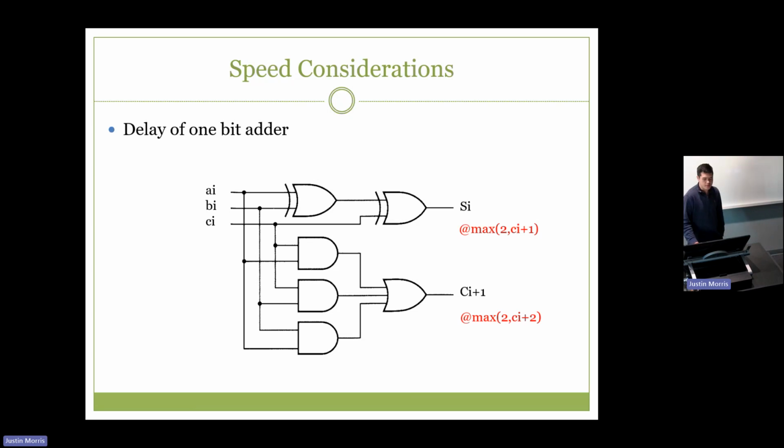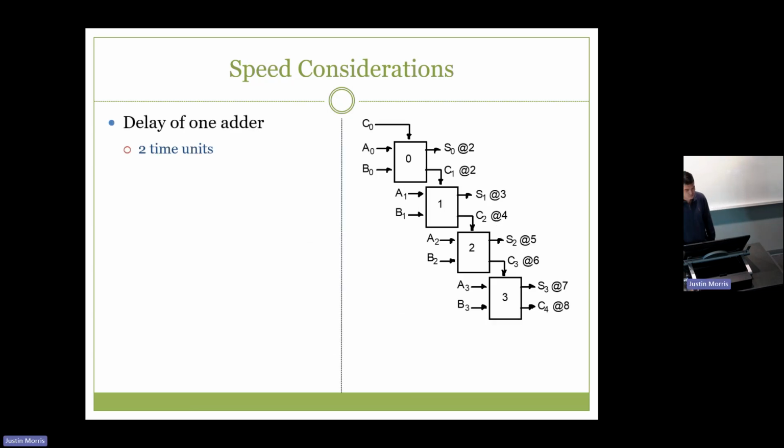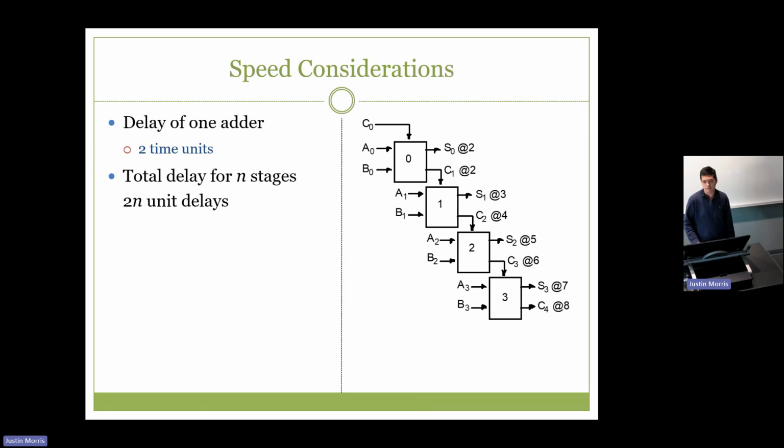And we talked about how we could connect all of these together to make a multi-bit adder by doing the ripple carries, but then you're adding for every bit 2 more gates of delay. So with this setup as our ripple carry, our delay is going to scale by the number of bits. And if we have too many bits, our delay is going to be too long, right?